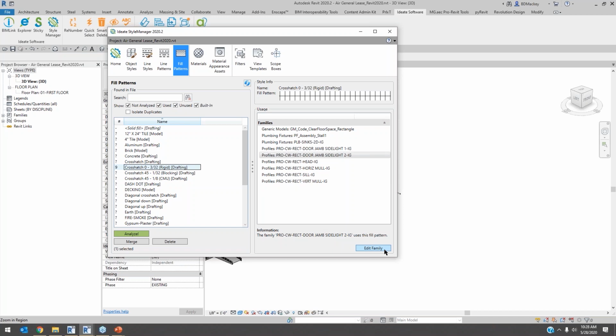It might bring in materials, or will bring in materials if you've got them. So personally, if I'm going to be saving it on the server, I never hit edit family from a project environment. I literally go open, find it on the server, and do it that way. So just a heads up, their tool does give that option to you. I wish we could right click and say open from server, and it would find the server path. That would be really sweet, rather than just editing it directly from the project.